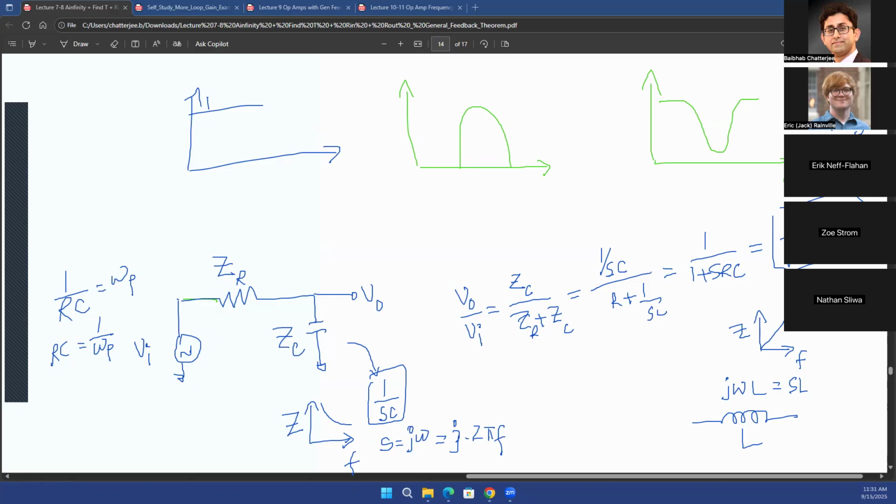We'll discuss this in more detail in the next class. But what this means is that that's why you'll have your 3 dB point, because at your 3 dB bandwidth, your signal value reduces to 1 divided by square root 2 times, which in power form is the square of this, and that means your half power point. The square of 1 divided by square root of 2 is equal to half, right? And that's where the half power point comes in. And after this, you'll see that as you increase your frequency, the value of the amplitude will go down. So this will be a low pass filter. We'll stop here, and in the next lecture, we'll start from this.